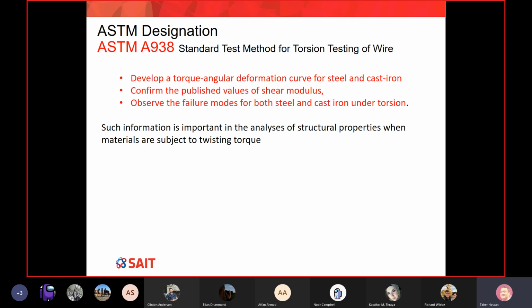We have a very similar number as a material property, but in shear. If we apply a stress in shear, the material will respond based on how rigid it is in shear. It's a very similar concept to the modulus of elasticity, which is for normal stress, and it's called shear modulus. We will learn about this a little bit later on.